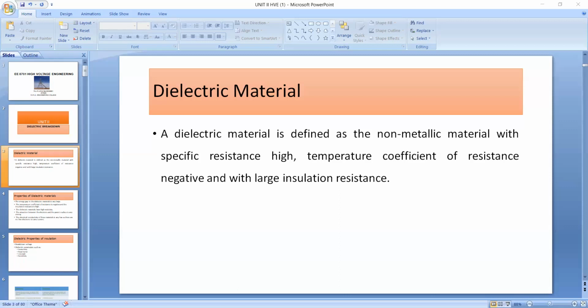Now, in order to find the constant, what is the n value at x equal to 0? When x is equal to 0, the number of electrons at the cathode n is the same as n naught, where n naught represents the number of electrons leaving the cathode and n represents the number of electrons at a distance x.